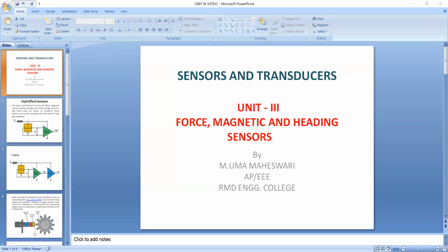So this Hall effect sensor is composed of a Hall effect element and a permanent magnet, and it is placed near the tooth of the disc, which is connected to the rotating shaft. The gap between the sensor and the teeth of the disc is very small. Whenever a tooth passes near the sensor, it changes the surrounding magnetic field, which will cause the output of the sensor to go to a high value or a low value.